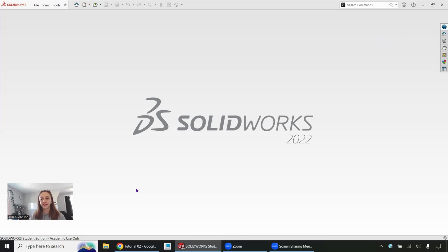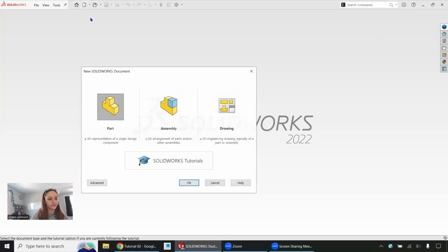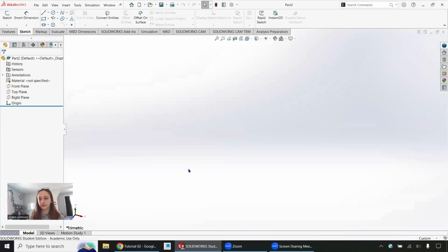In this video, we're going to get started with the sketching tool in SolidWorks and get familiar with the different entities available for us. The first step is to create your file. So I'm going to hit New up here, and I'm going to choose a part. First thing I want to do once my part is open is save.